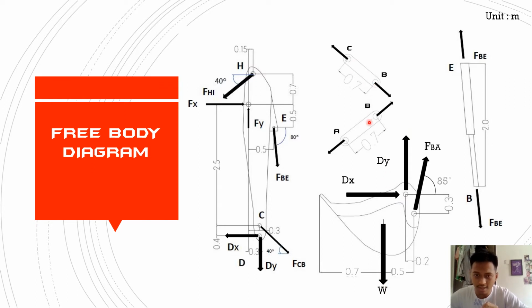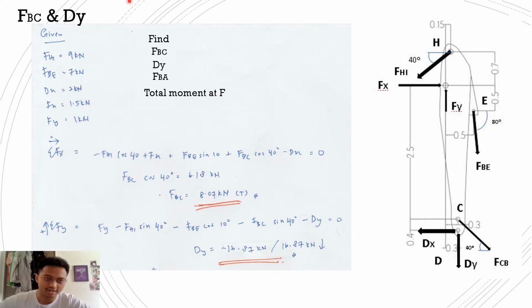For the CB and AB members, we assume both members experience tension force. Therefore, the arrow at both ends of each member is going out from the member. For the member EB here, we assume it also experiences the tension force. Okay, now let's move to the calculation.